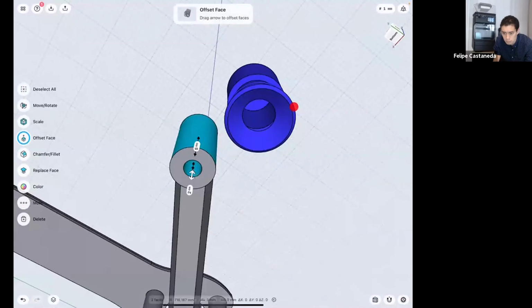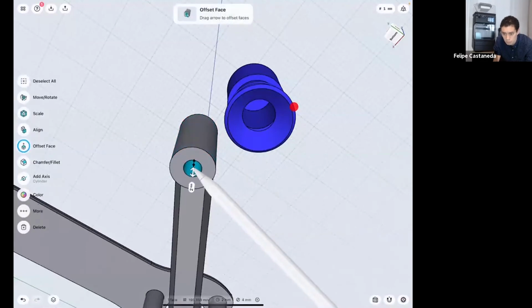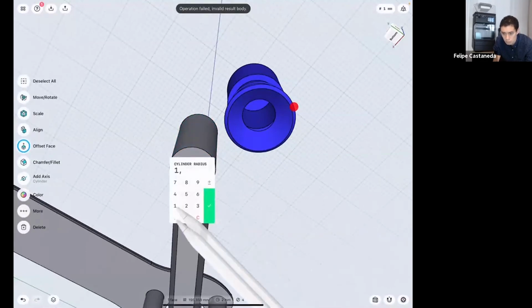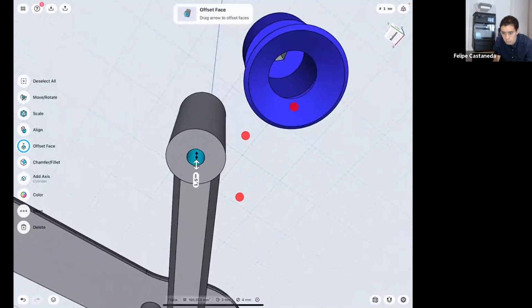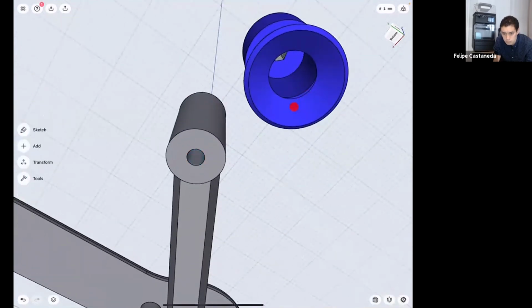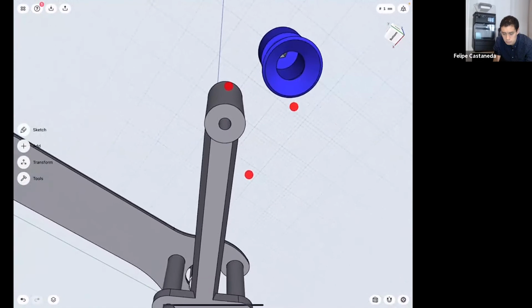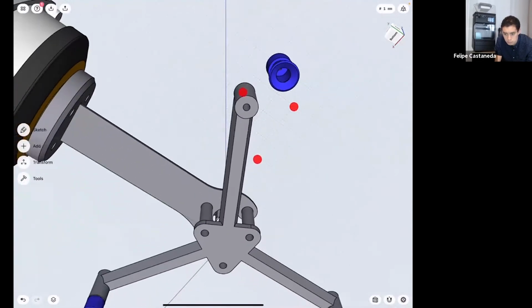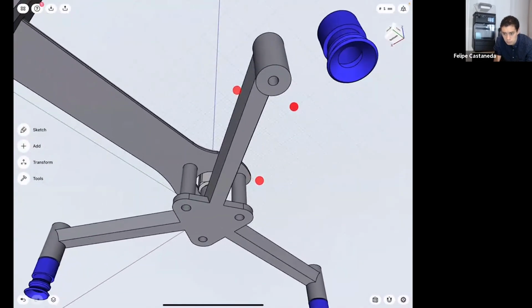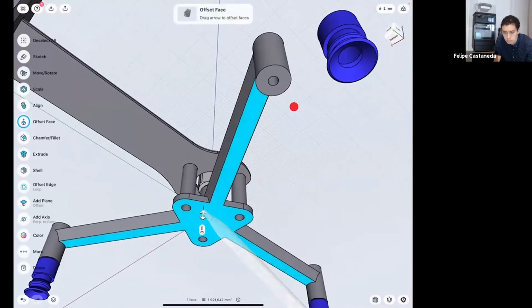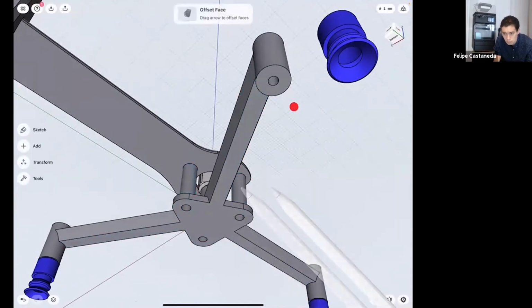So I can make this hole smaller by selecting only that hole and making it, let's say, 1.5 millimeters. To change the whole wall thickness of the gripper is not what I would do in this case, because it is so complex with this face and all the mounting points that it would break the model.